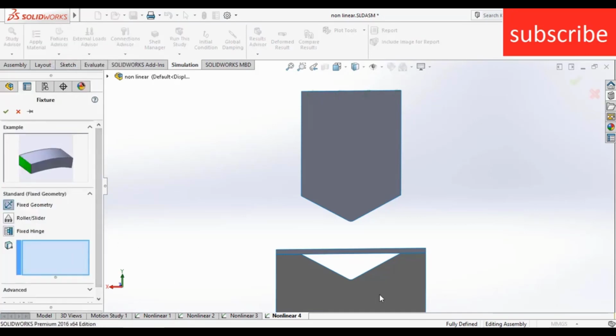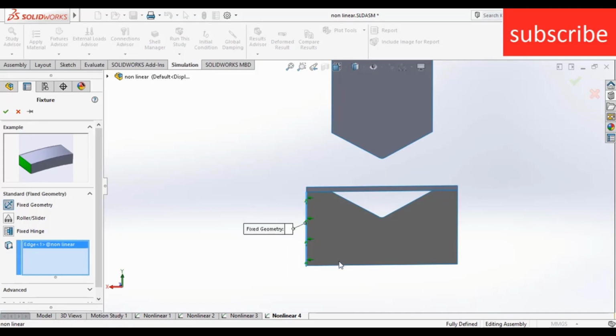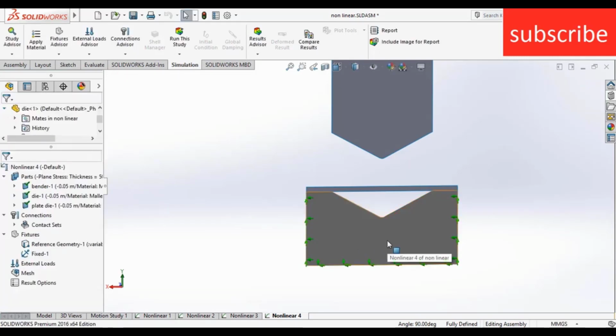Now select the bottom of the die, click on fixed geometry. I think just remember one thing, it doesn't matter what you do while assembling, fixed anything or not. While doing simulation, you need to redefine what is fixed or what is not. If you don't, your simulation is not gonna work properly.